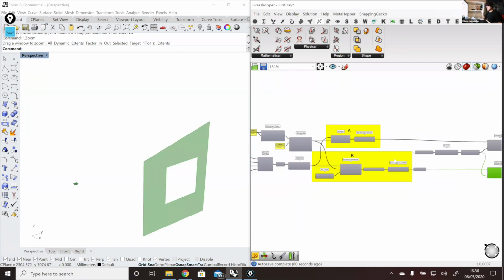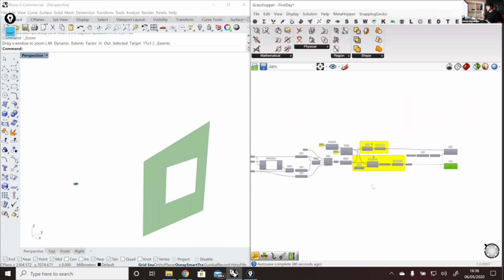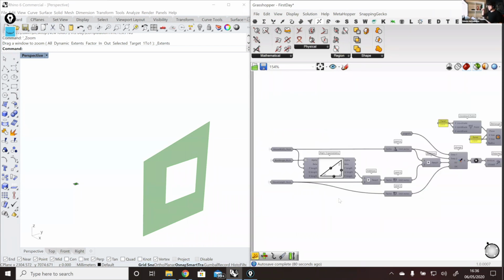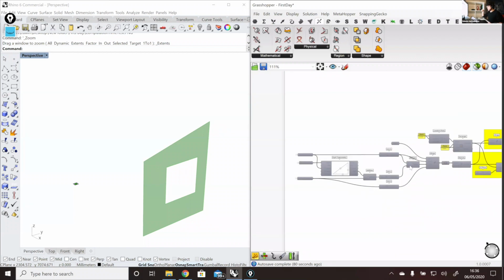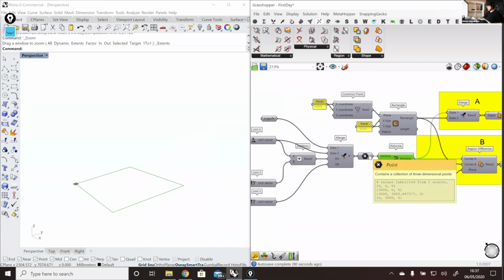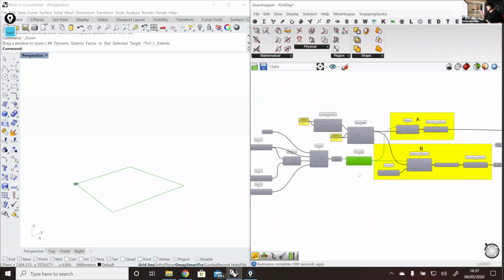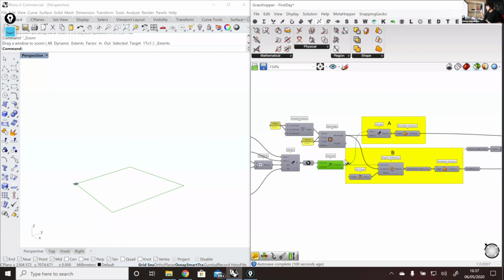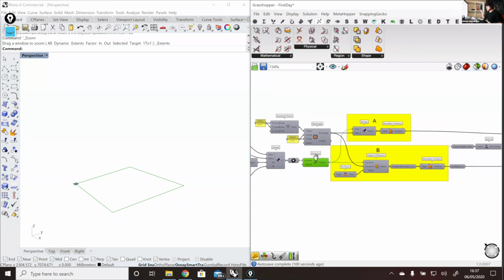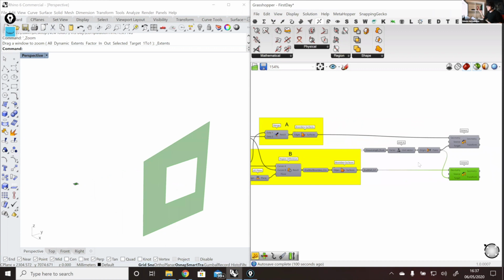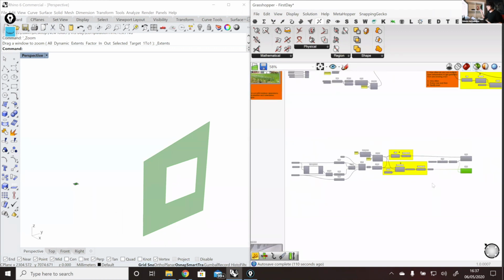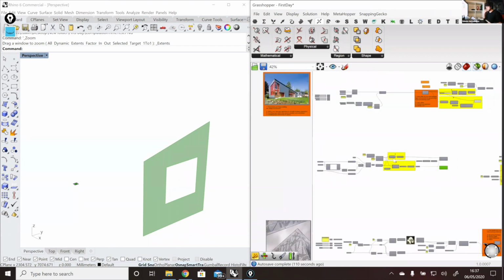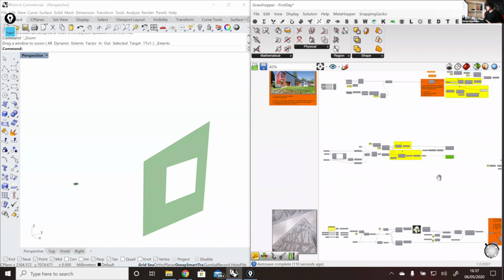And in this case, of course, we will use data trees to create each of these walls on the ground. So we will see here, instead of a single tree with 4 points, a tree with 4 branches, because we have four walls, and each of these walls will have 4 points that construct our polylines. So we'll use data trees here. We will check that tomorrow, and create each of these walls and position them at the end. So this is how we would do it, creating each of these walls from scratch. So this is the first part, our first example.